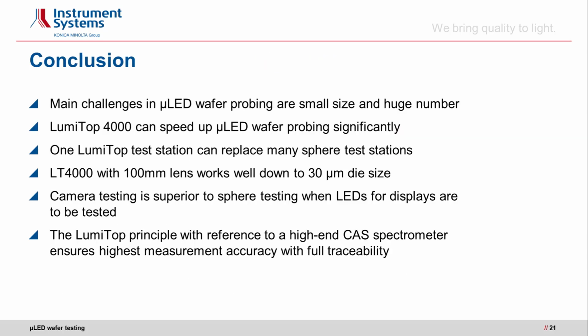I would like to summarize a little bit what we have learned during this presentation. We have seen that the main challenges in micro-LED wafer probing are the small size and the huge number of LEDs on the wafer. The Lumitop 4000 can help to speed up micro-LED wafer probing significantly. Remember, 42 hours with the integrating sphere, only 1 hour with the Lumitop 4000. Therefore, one Lumitop can replace many sphere test stations.